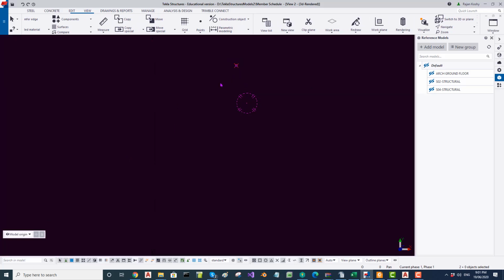I can individually inquire and see the X and Y, but this is not the best method. Don't get misguided. This is not the best method. It should be architecture files you should be inserting. You should match the grid lines or some identifiable feature. Here I am adding structural drawings because we just want to place some columns, that's all.